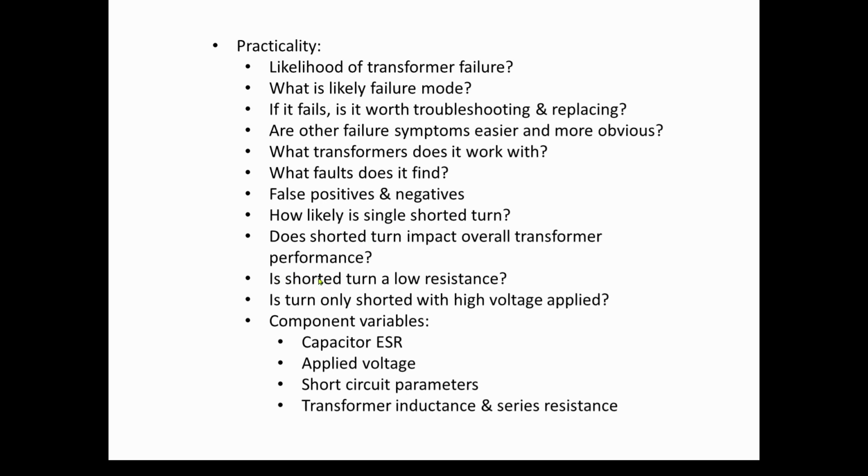And a very important thing is the characteristics of the short-circuited turn or turns. Is it really a low resistance? Is the turn only shorted when high voltage is applied? Maybe it's damaged the insulation, but still it's got some insulation, air insulation, and maybe, in order to recreate that short, you need to apply a high voltage.